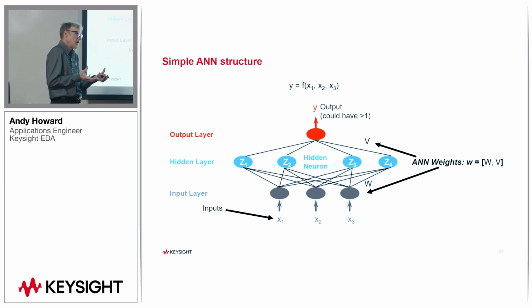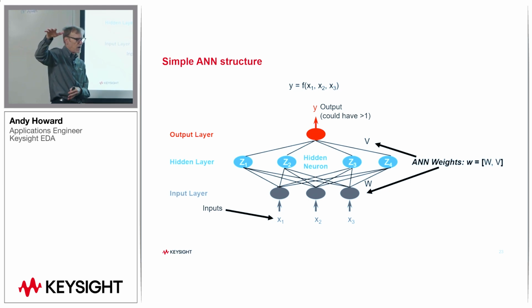It's an equation-based model. You have all this data. You have a bunch of measured load pull data. The measured data is things like output power, efficiency, gain, maybe bias current. Various things have been measured. The things that have been swept are the load tuner impedance, the input power, and possibly the frequency.